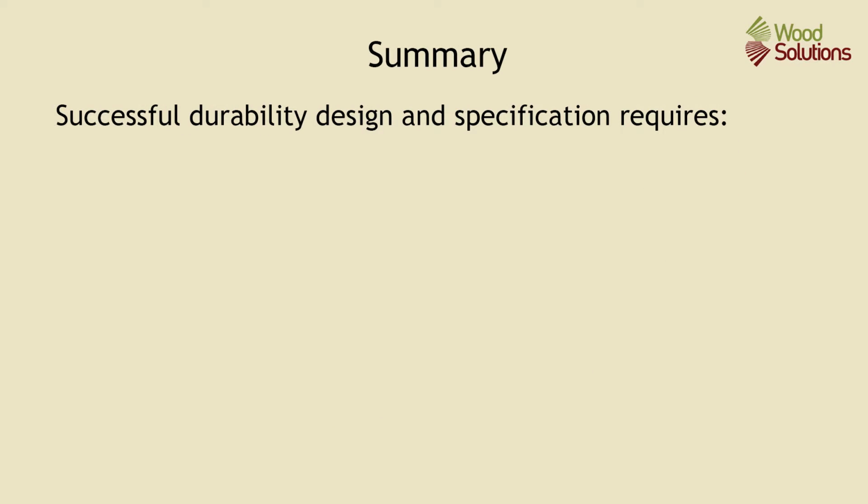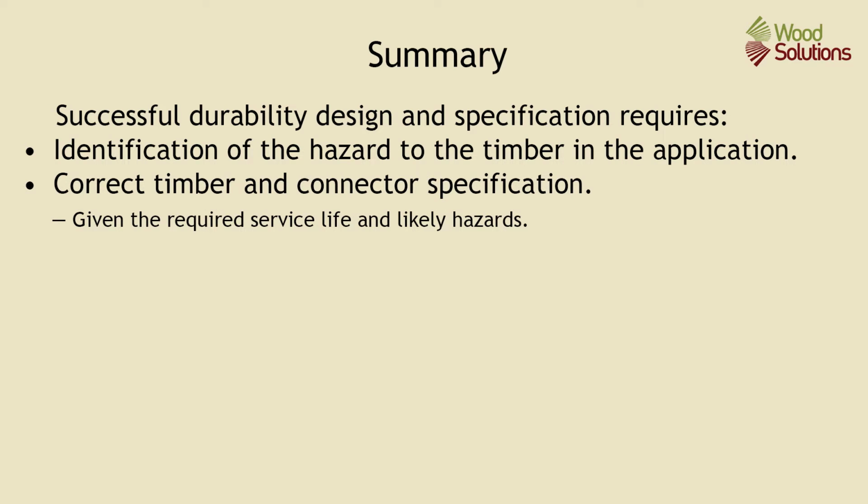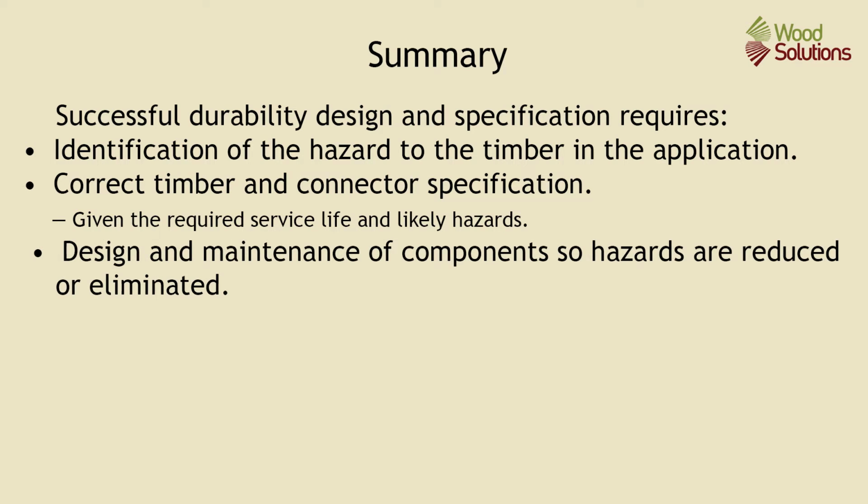So, in summary, successful design and specification for durability requires identification of the hazards to the timber in the application, correct timber and connector specification, giving the required service life and likely hazards, and design and maintenance of components so hazards are reduced or eliminated.